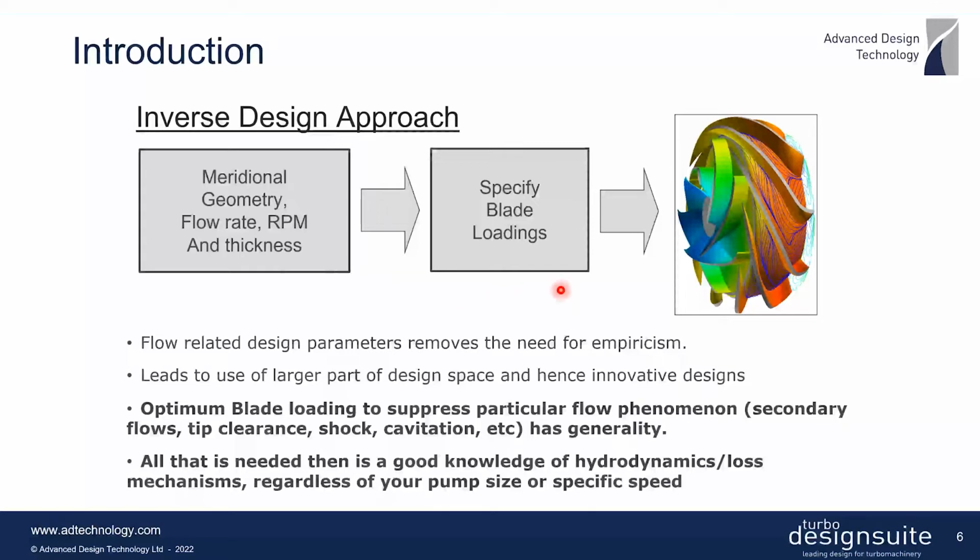Once you have a good understanding of your specific flow issue, whether it's secondary flow, corner separation, or cavitation that you're dealing with, it's possible to come up with guidelines on the optimum blade loading to tackle each of these issues. And actually, this know-how has generality, which makes it suitable for all your pump applications.